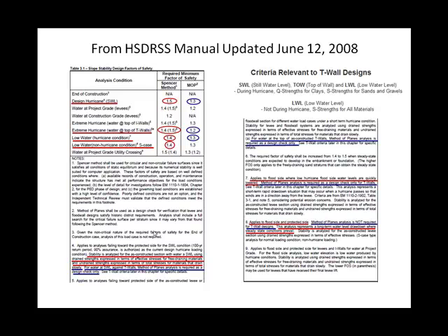As I mentioned earlier, the method of planes is only used as a design check for the Spencer's method, and in the case of the non-hurricane condition, the method of planes is not used at all for that particular criteria.